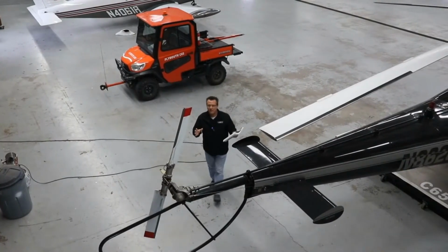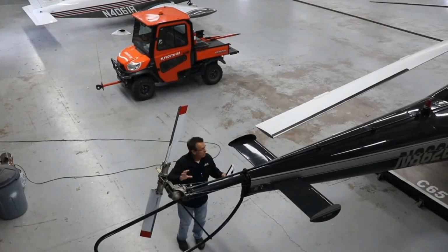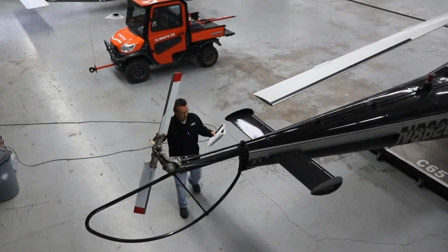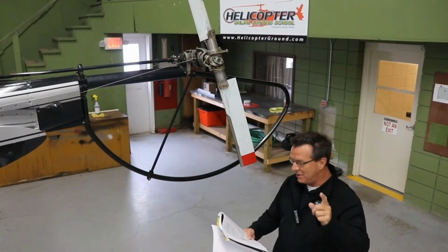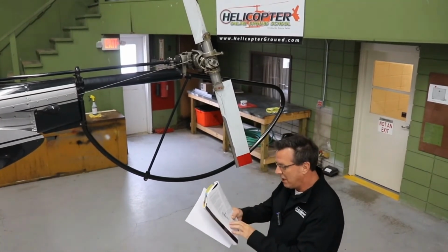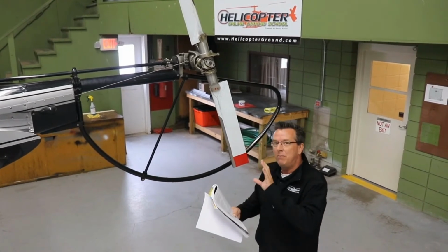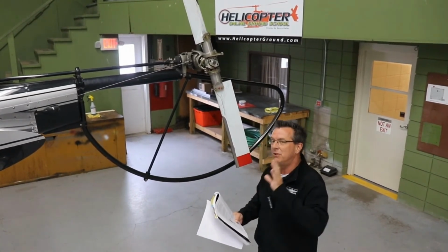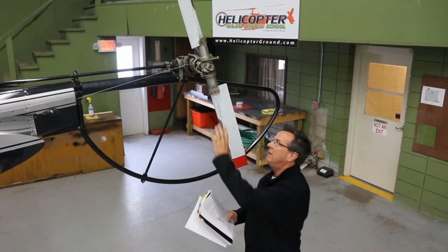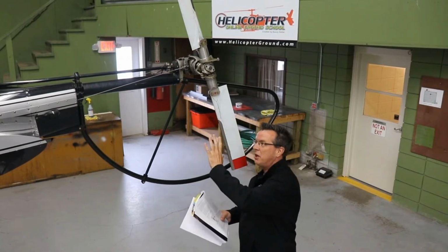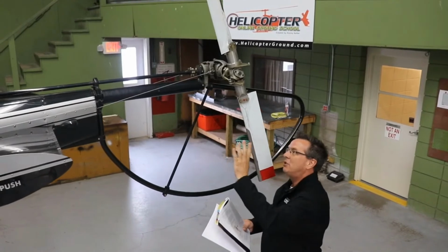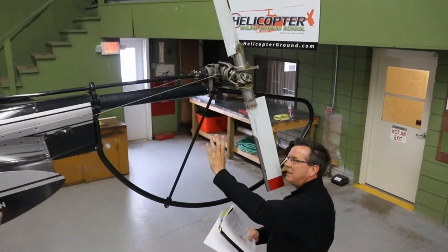So we have to counteract that torque. And the way that we counteract the torque is the tail rotor, also called the anti-torque rotor. Even though we're talking about translating tendency or tail rotor drift, we just want to point out this quick point, because it shows us right here: tail rotor downwash, tail rotor thrust. And people are messing this up on check rides, and our examiner said, please, when you're doing your videos, start really pointing out these things that people are struggling with. So the tail rotor's back here doing its job. It's pushing against the tail boom, okay? So it's counteracting torque by pushing against that tail boom.